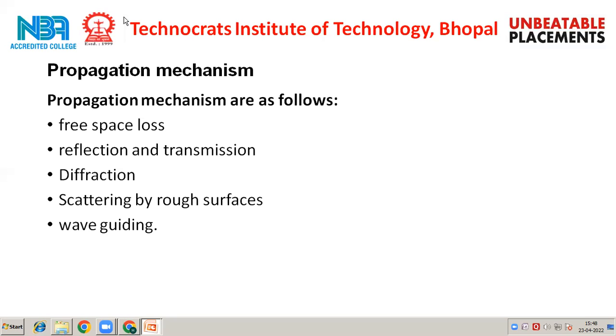Also, in a radio communication system, the propagation of the modulated signal is accomplished by means of a transmitting antenna, the function of which is twofold. The very first is to convert the electrical modulated signal into an electromagnetic field. In this capacity, the transmitting antenna acts as an impedance transforming transducer, matching the impedance of the antenna to that of free space. And the second one is to radiate the electromagnetic energy in the desired direction.